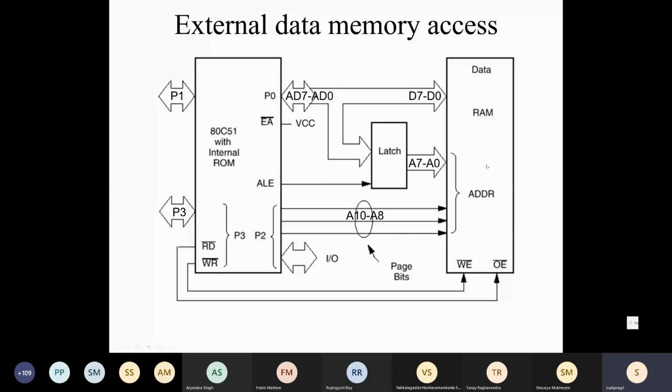Okay, but it is always in groups of bytes. So you cannot do bit by bit writing or reading operations from either the program memory or the data memory. It's always a chunk of 8 bits at a time. Even if your data may not be valid for 8 bits, let's say 4-bit data is there, you have to do read or write in 8-bit chunks. And if it is obviously more than 8 bits, then 2 bytes must be accessed one after another.